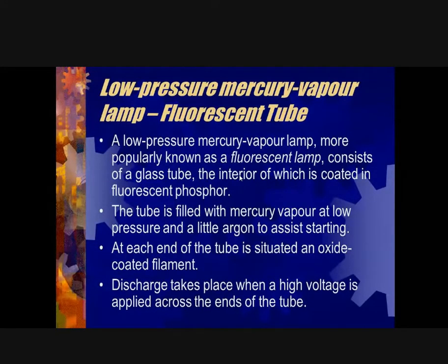If it's a T8 type, you follow the connections that are shown on the tube, and so on. So you have different types of connection for the tubes. Before you actually put an LED tube into a circuit, you need to identify the type of LED tube you have. Sometimes you have to make modifications to the connection before you can actually change the tube.